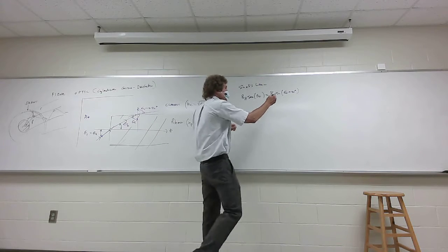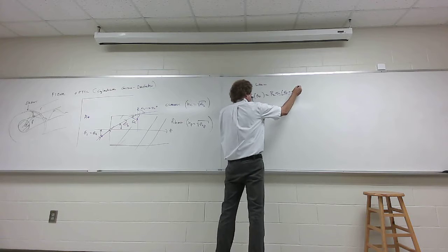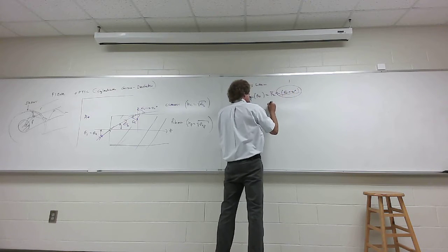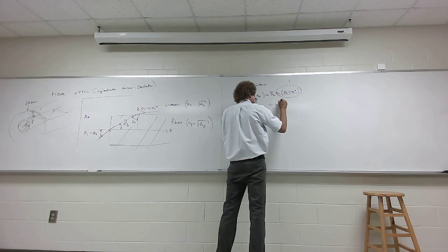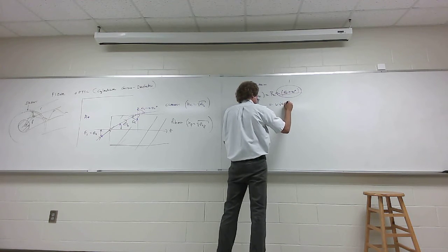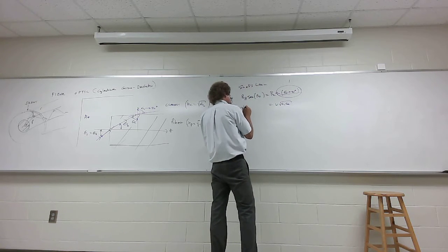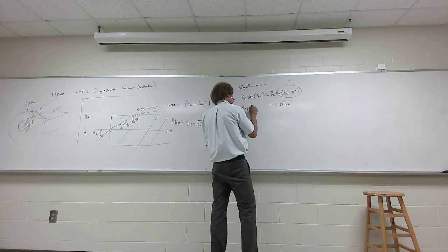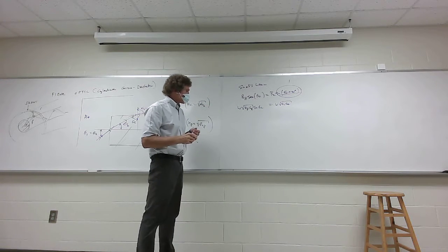Right? So we set this angle equal to 90. That means the sine of this becomes 1. Now we get beta cladding, which is omega, really, times square root of mu cladding, epsilon cladding, equal to omega times square root of mu fiber, epsilon fiber, times the sine of theta cladding, or theta C, according to the drawing.